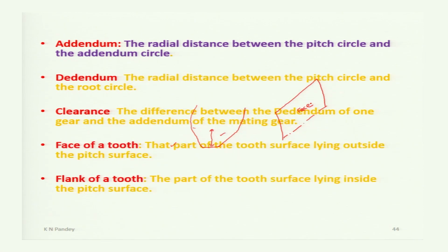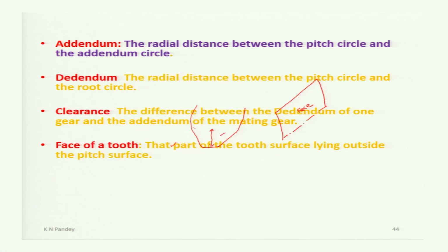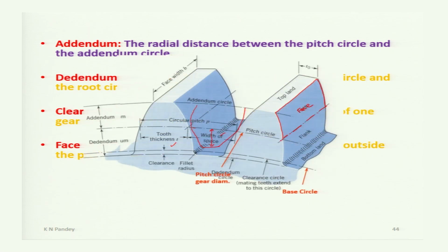Then the flank of a tooth is the part of the tooth surface lying inside the pitch surface. So if we see that, this part below the pitch surface is the flank. So this part is the flank below the pitch surface, and this above the pitch surface is the face.